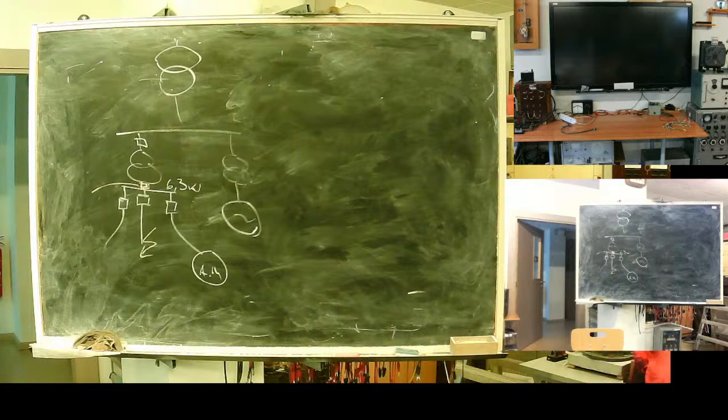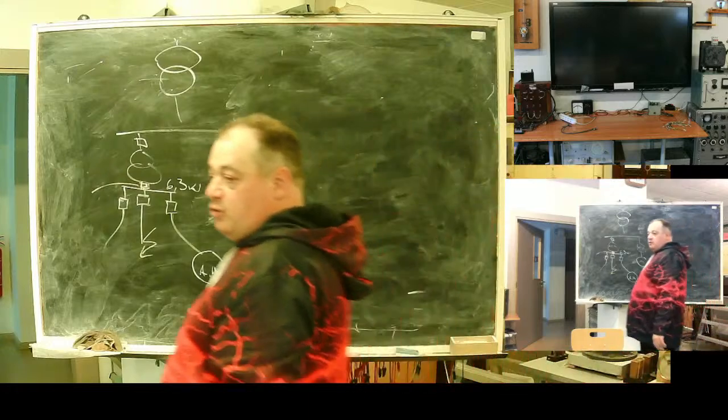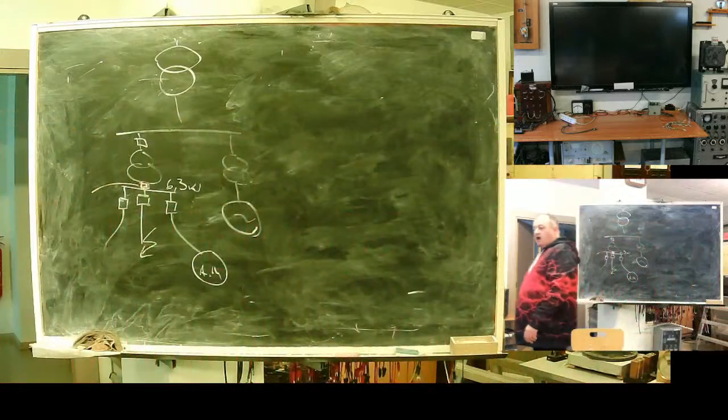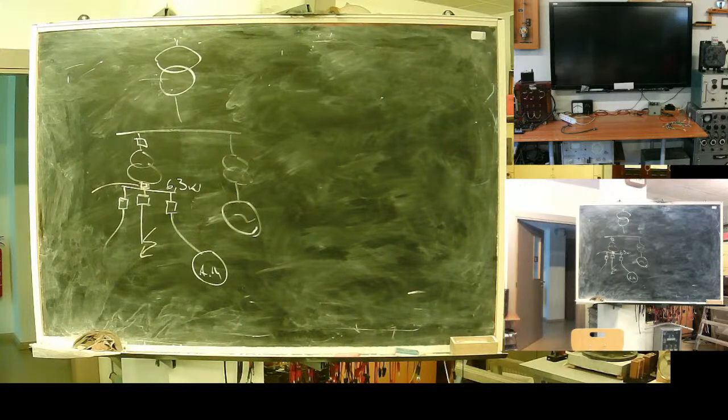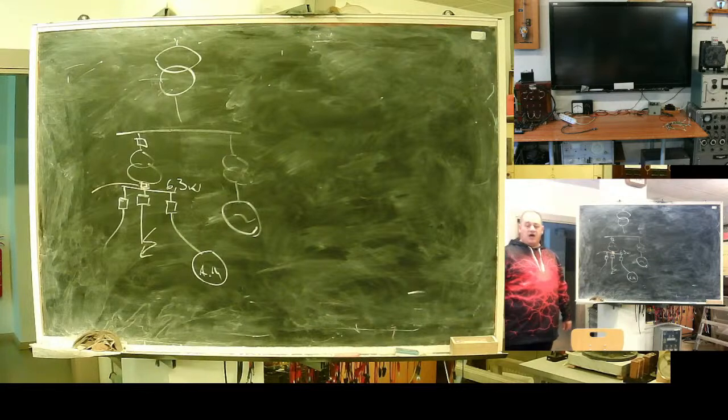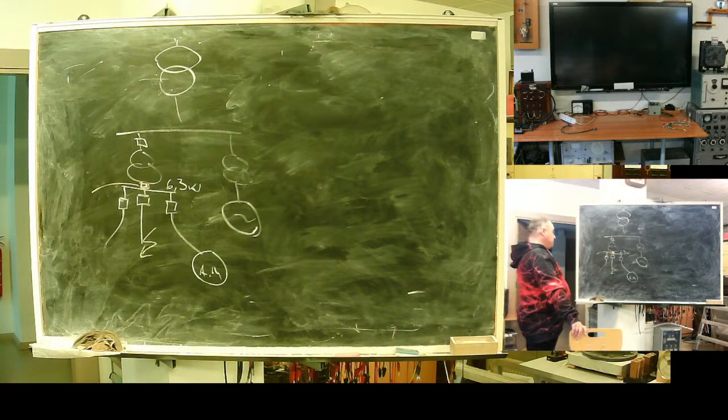No switch in this world connects the poles simultaneously. The first two will come in connection first, so at the first moment you will see a line-to-line fault turning into three-phase. Even if it's an earthing knife or an earthing ring left after repair work.